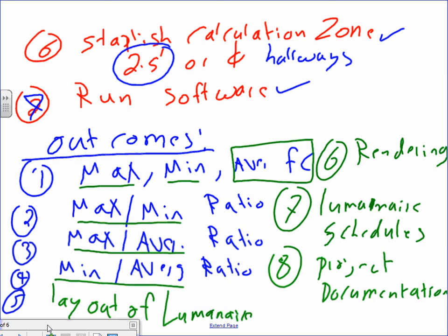and you will get the foot candle for every single spot on a 12 by 12 grid, 12 inches by 12 inches, guys, or 2 feet by 2 feet, I believe, by default. Everywhere inside. I think 10 by 10 is outside, or maybe 5 by 5 feet, depending on where you need the calculation. You can change it. You want to make a calculation on a grid of 2 feet by 2 feet, or you want to make it a grid of 4 feet by 4 feet. Typically 2 by 2, I believe, indoor, outdoor 5, or 10 by 10.